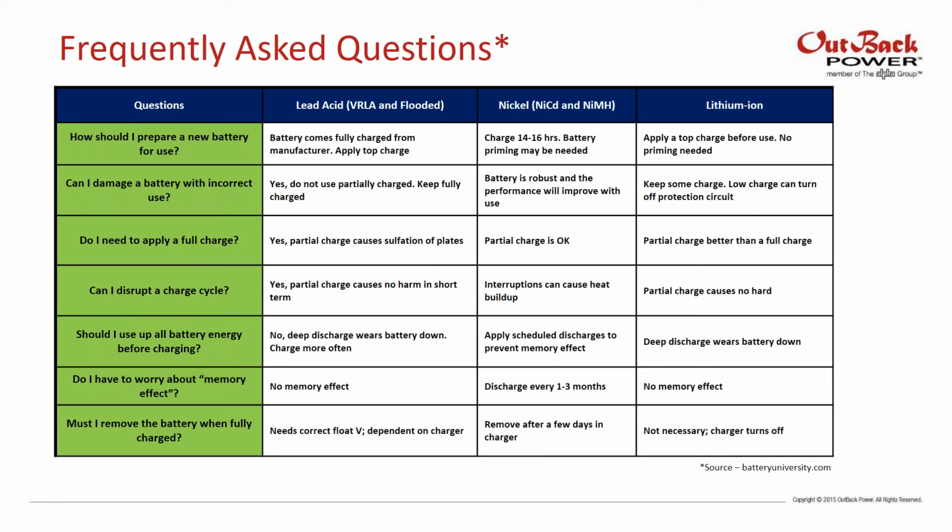And do you need to apply a full charge all the time? Lead acid, this column says yes, partial charge causes sulfation of the plates. That's true for most batteries. There are certain kinds of lead acid batteries, for instance, the Outback 200 nanocarbon, so NC batteries, that do operate fairly well at a partial state of charge. And then for lithium, obviously partial charge is fine.